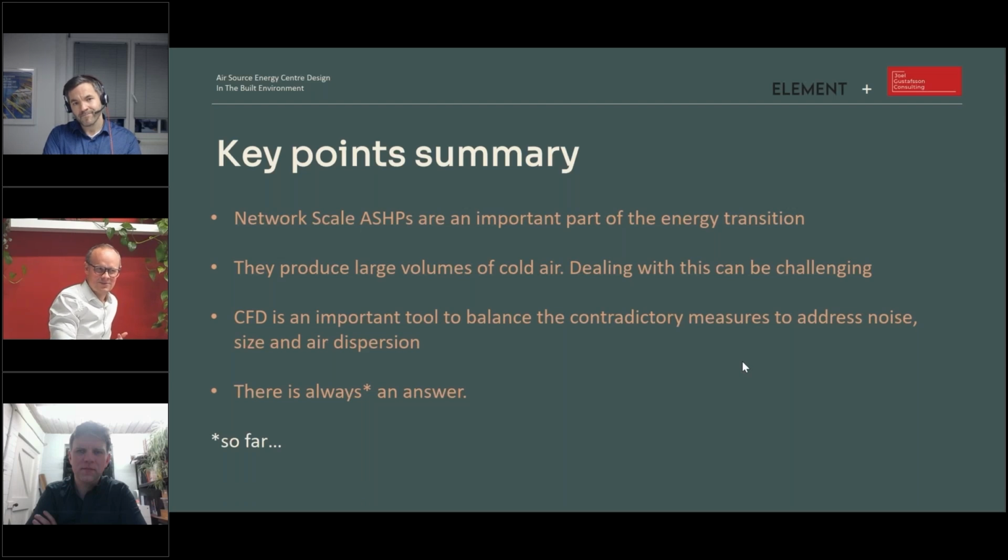And this is quite extreme in some instances. I had a much smaller project inquiry come to us. It had planning, it had listed building consent, and the air source heat pump was literally in a completely enclosed box with a roof. So people, that is an indication of the level of misunderstanding of what these pieces of equipment do. If they don't move air, they don't work.